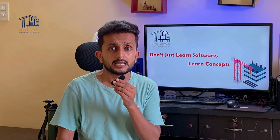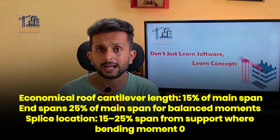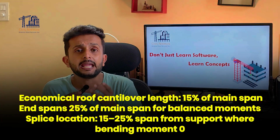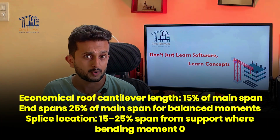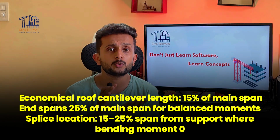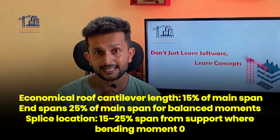In the next phase, let's understand roof cantilever and splice locations. In case of a single story roof with uniform load and equal spans, the economical roof cantilever length will be 15% of the main span. Similarly, end span will be 25% of the main span for the balance moment, and you can identify the splice location based on 15 to 25% span from the support where the bending moment is 0.